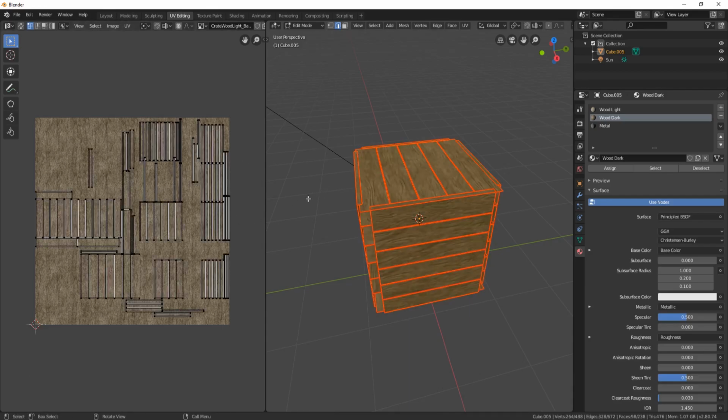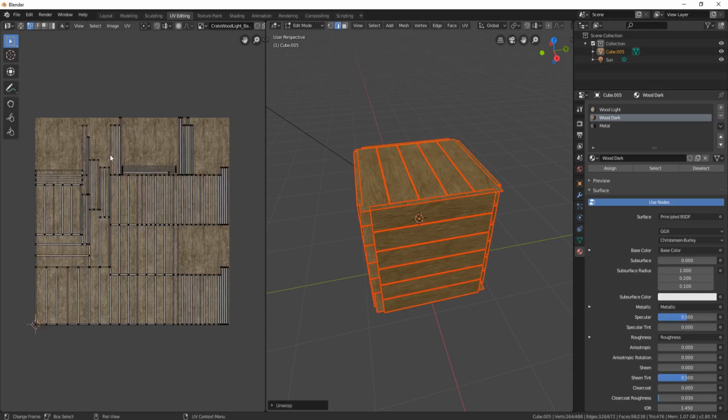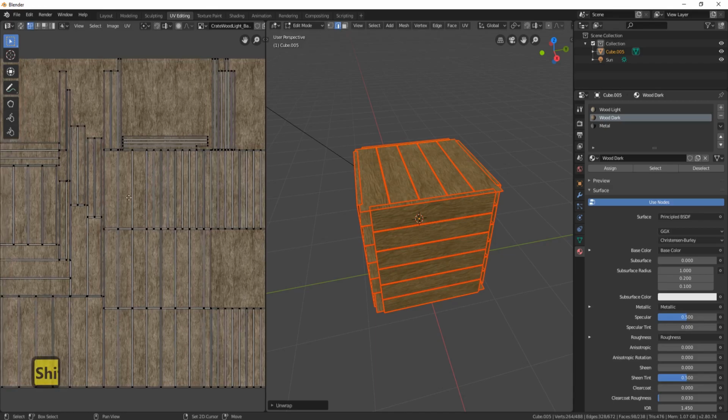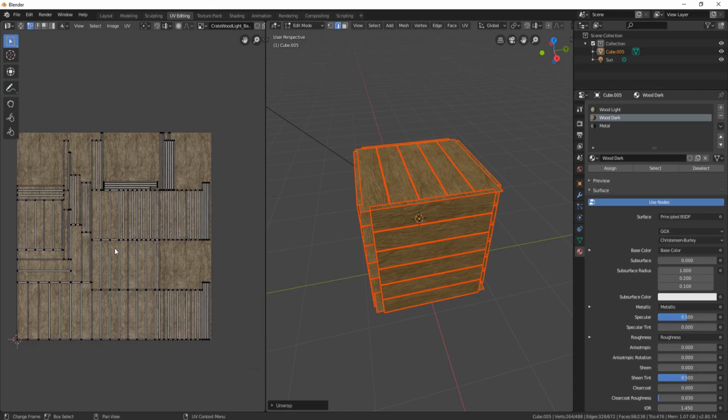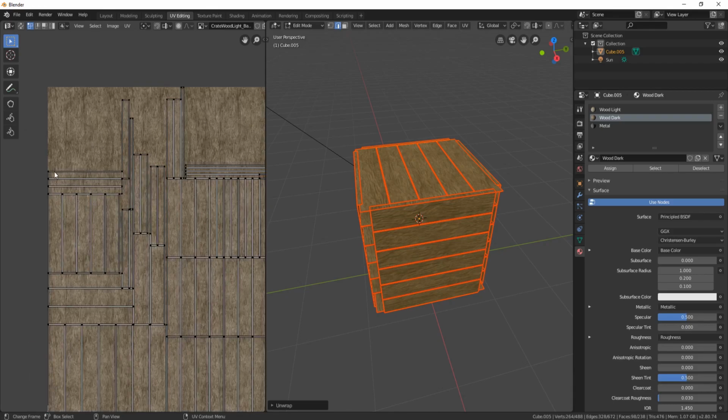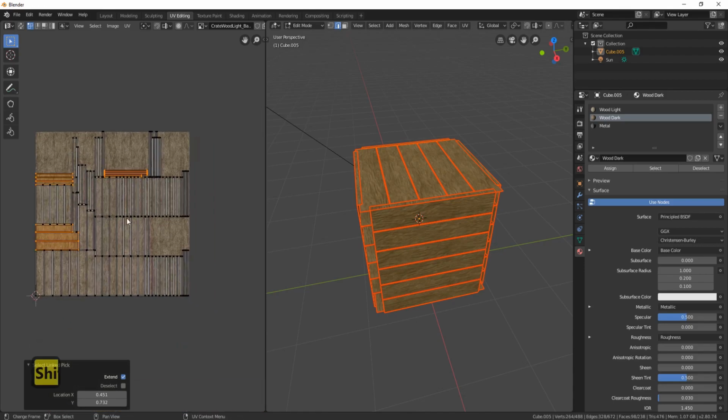and you can see these are unwrapped like this. So press U for unwrap, that'll unwrap them like this. And now we need to simply go in again and turn the ones that are facing the wrong way, which is these. You can see they're going this way. So just turn them around. So I'm going to go in and press L on the ones I want to turn around. And just make sure you grab them all. And that looks like them all. So R90, let's turn them around.